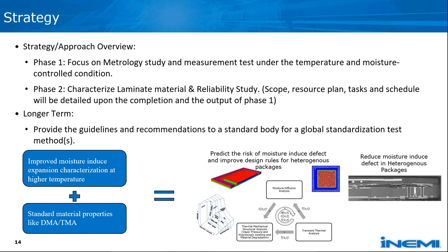By knowing the full reflow temperature range swelling properties, we will be able to make better decisions and ultimately better products through better material selection process, improvement of material formulation, better predictive capabilities, and improving design rules leading to reduced failures.